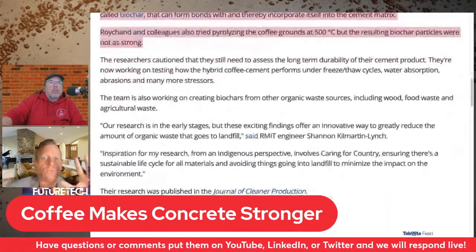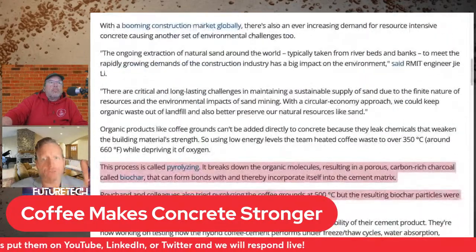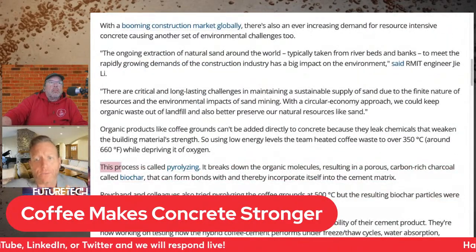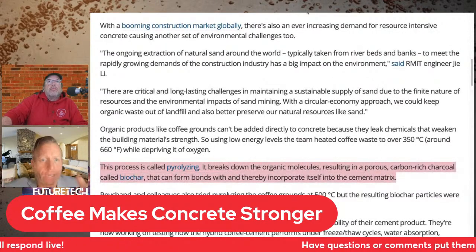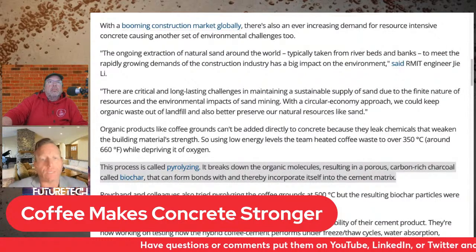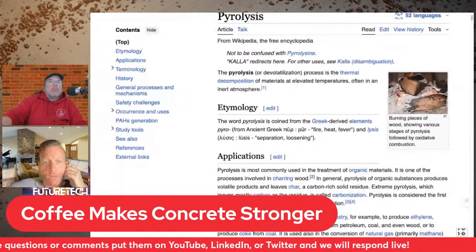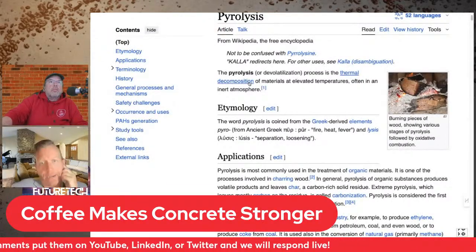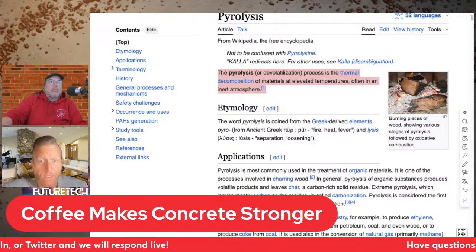by weight. So what pyrolysis does is it transforms the organic compounds in coffee grounds so they integrate into the concrete instead of weaken it, so they kind of mix in and help to strengthen it. And the heating occurs in an oxygen limited environment, so the biomass does not combust.